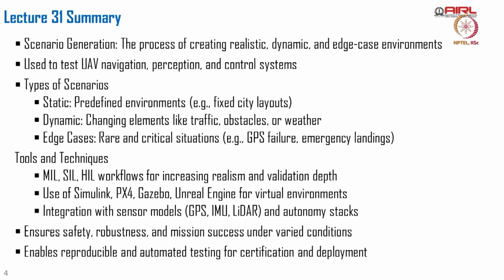For example, you can talk about GPS failure, or foliage coming into the picture, and if the drone is not getting GPS for a distance between, let us say, 10 buildings, how is the controller going to work, or how much is the drone going to deviate from its path. Or we can even talk about emergency scenarios, how the drone is going to respond, or we can inject winds in those scenarios and see whether the drone still continues to track or not. All these can be evaluated, visualizing the performance of the controller in a 3D world.